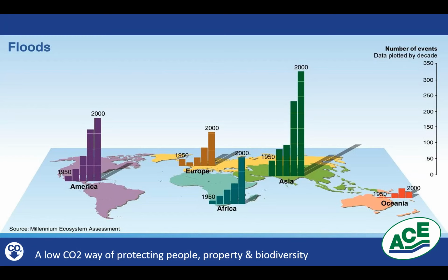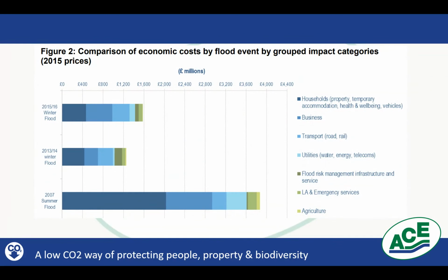Now, what this means is our historic modelling for flood defence structures typically was always to design a structure for a 1 in 100 year event. The problem is that now 1 in 100 year events are happening almost every other year, as you can see when I move to this slide. So this shows 3 recent floods. It doesn't include the flood that we've had earlier this year. So it's only 3, but these are all 1 in 100 year events, and you'll notice that there's not 100 years between them.